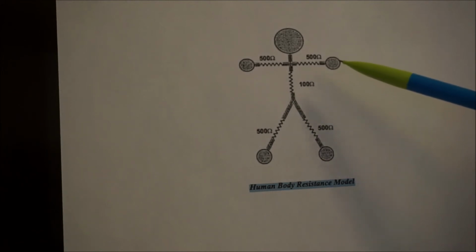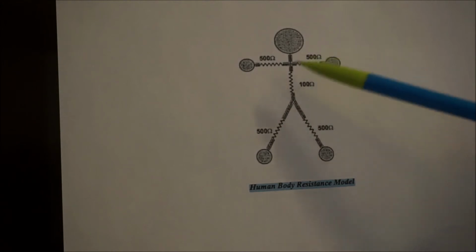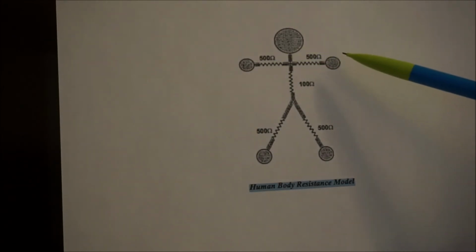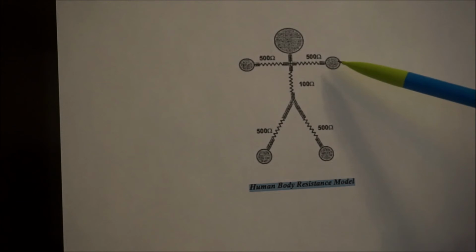If you're working on a 400 volt B plus rail in your tube amp, and you get in contact with the chassis to that B plus voltage, you could possibly get, according to Ohm's law here, 400 milliamps through your heart. So that would probably definitely stop your heart, and you could have severe burns and stuff like that.